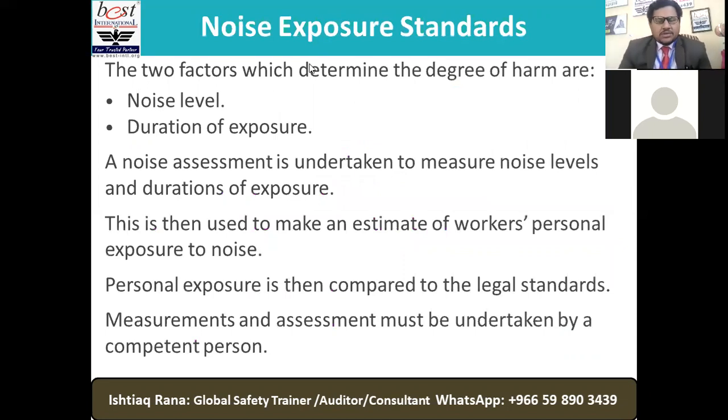Now, there are plenty of noise exposure standards, but bear in mind two factors which determine the degree of harm: noise level and duration of exposure. If the persons are working above 105 or 106 decibel, then the second parameter is important: how many hours they are working in that area. Whether they are working for 8 hours or more, or for 1 hour, because of this duration of exposure, the impact will be lesser or more.